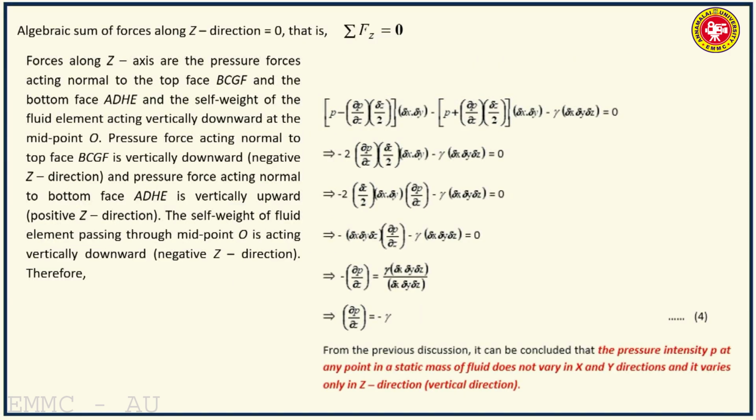So let us examine. Now let us consider the third mutually perpendicular direction, that is z direction. Sigma Fz is equal to 0. That is the bottom face and then the top face. And then in addition, you have got one more force, that is the self weight of the fluid element. So here you have got three forces.